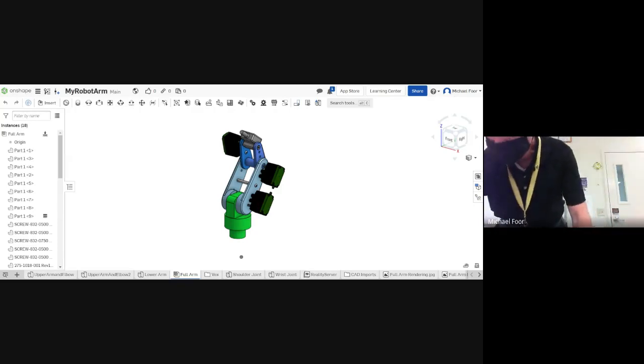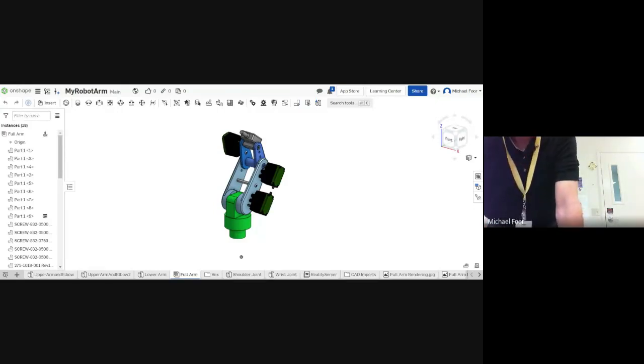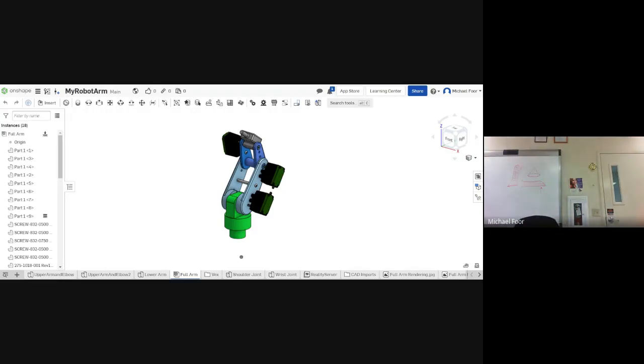I think it'd be easier to crack from the bottom. That has a much easier place to work around. Oh, I don't know which one I want to do. Why so bad? If you hover over the red on the project tree, it'll usually give you a description of the error so you can see why it won't regenerate properly. Oh, it's on my rotation. Alright, one more try.